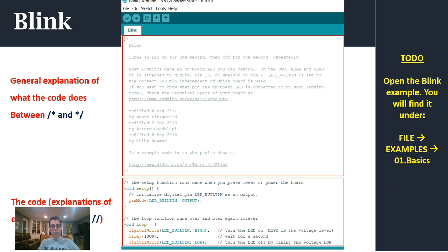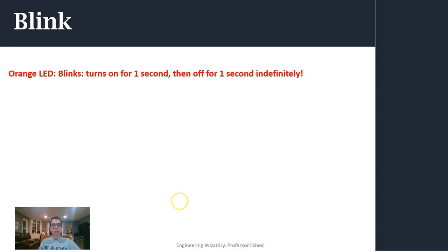Then the next command says send low voltage to the LED, and low voltage is 0 volt. 0 volt basically turns it off. No voltage, no current, then the light is off. Right after, and I didn't copy it in, it has another delay for 1000, so it waits another second, and that's the reason why it goes on for 1 second, off for 1 second. 5 volt, wait. 0 volt, wait. That's what it does: turn on and off, and wait 1 second in between.